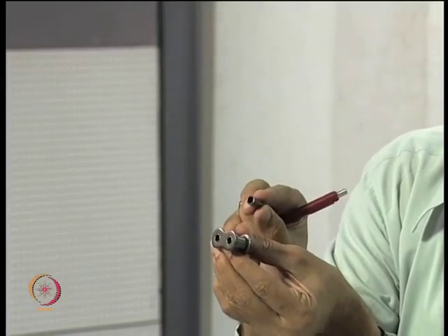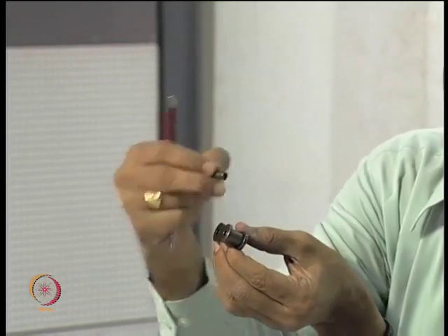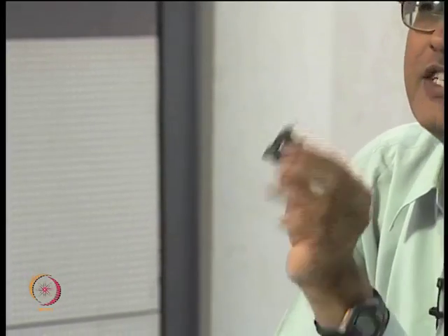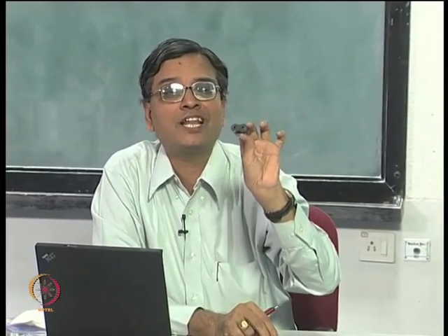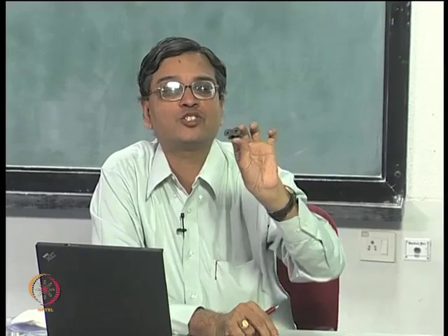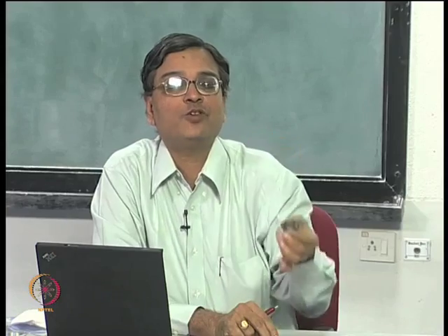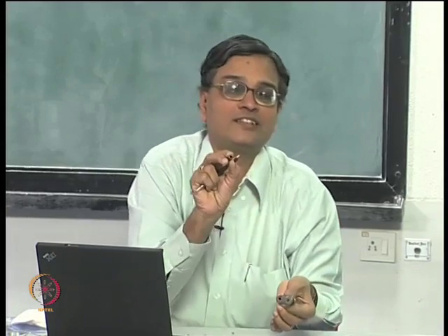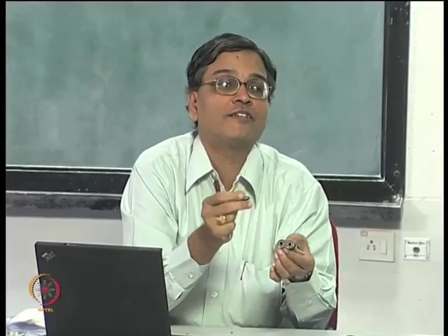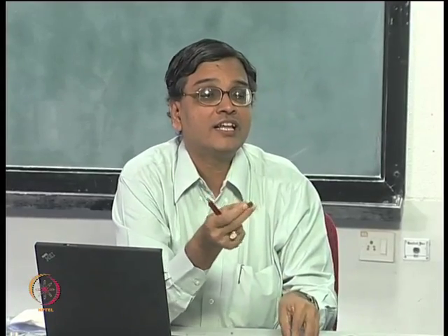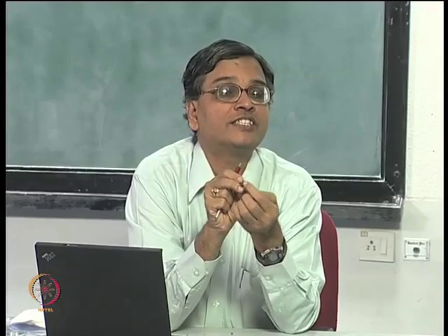So, suppose I do an experimental analysis on this component directly, which acts like a prototype, then I capture all the manufacturing variations that have gone into the fabrication of this. Whereas if I do a numerical analysis, I would take this as a perfect cylinder, I would not model if there are any fine undulations on the surface of it, and such variations do exist in actual practice.